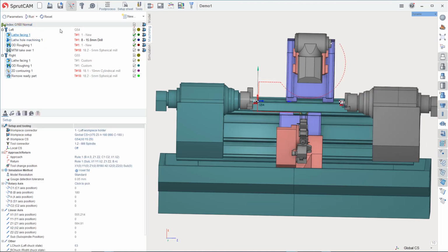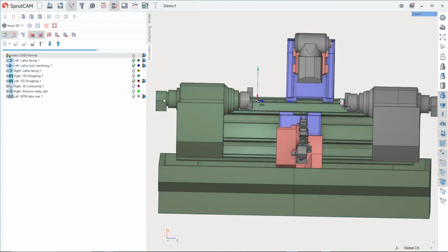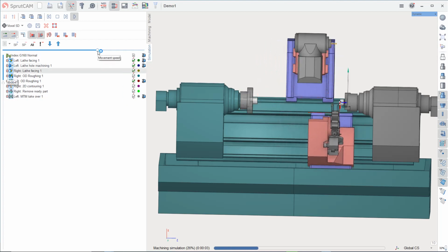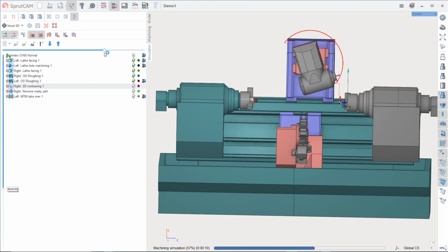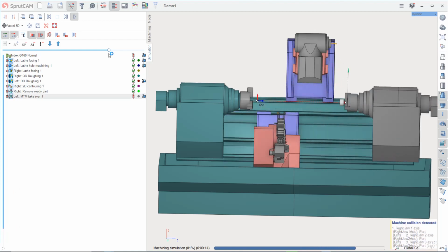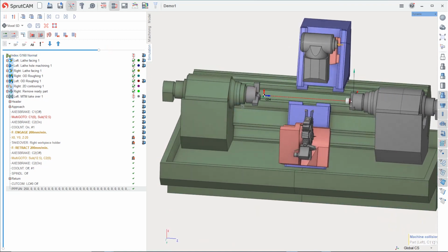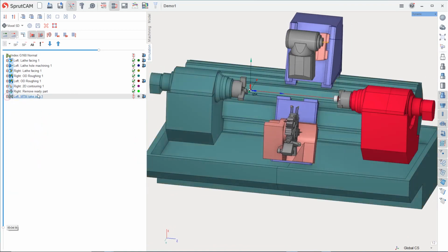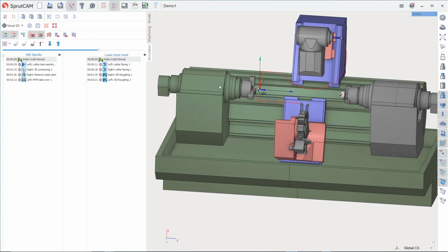Recalculate everything. After that, switch on. Calculate the links. After that, go to simulation and check again. Facing, drilling, roughing, another roughing, contouring, move. Looks good, but it's still not the actual process, because we need to define the multi-channel mode. Okay, if I try to run it in this way, we will see a lot of